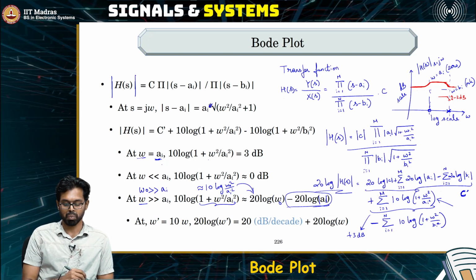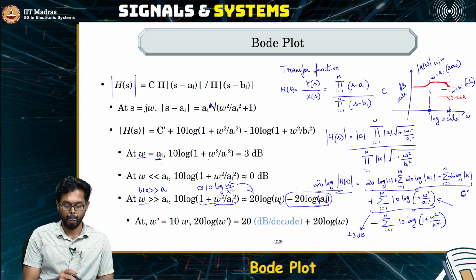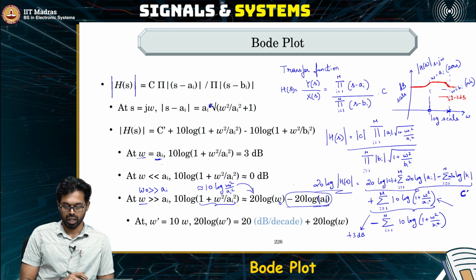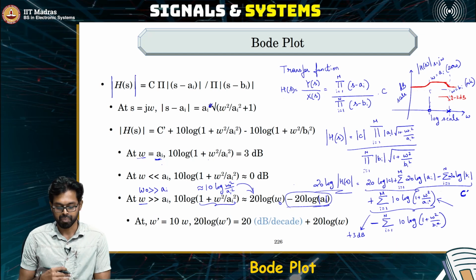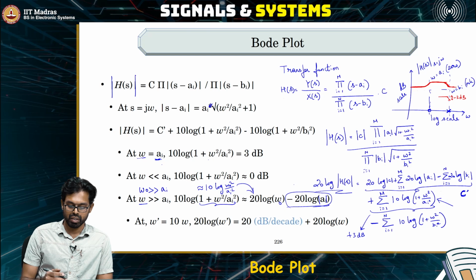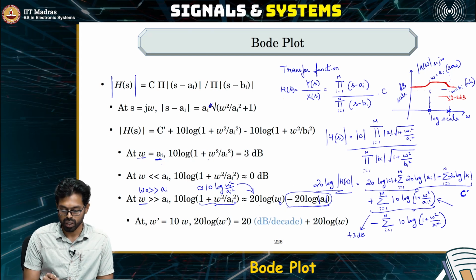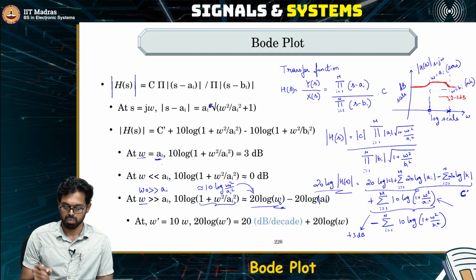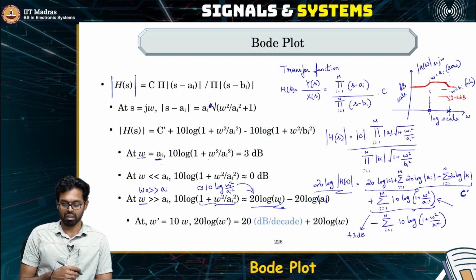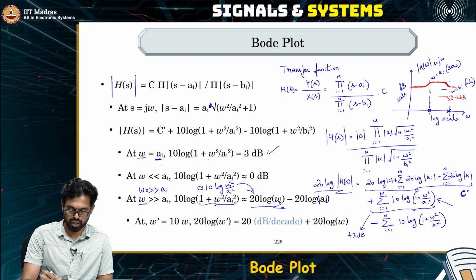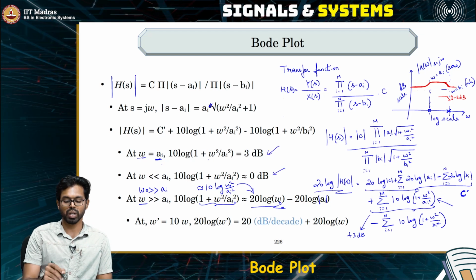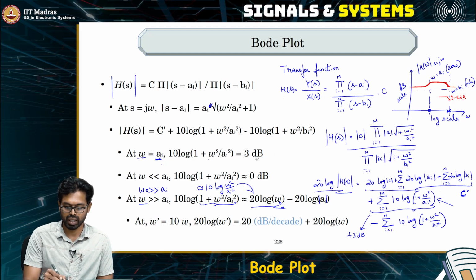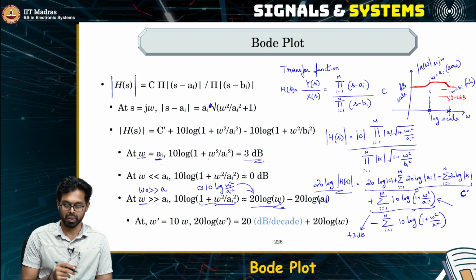So if you try to compute the transfer function's value away from the zero or pole, at a frequency which is much greater than the zero or a pole, then we see that the transfer function's magnitude is a function of the frequency itself. Because of that, we cannot make a comment like how we did in these two cases. In these two cases, we were exactly able to say that there was no contribution, or the contribution was exactly quantified by this amount, 3 dB.